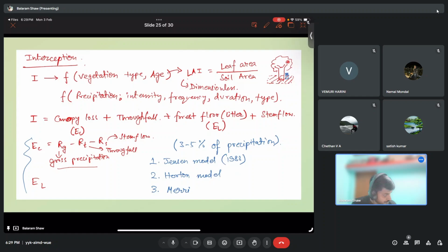So depression storage or ponding is any water on a drainage basin that drains into closed depressions, and this directly never reaches the outlet of the basin. If there is a huge amount of water in a depression storage, then it can flow as base flow or groundwater flow, or it can get evaporated at the end.